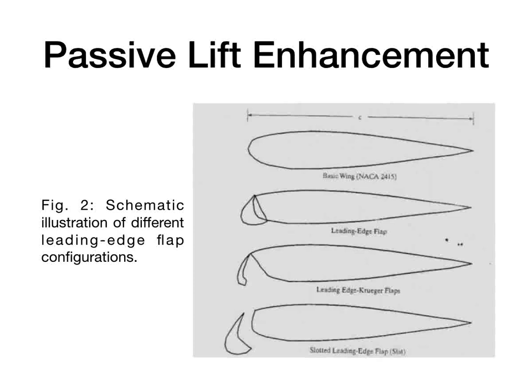A leading edge slot works the same way as a slotted flap, but allowing air from the high pressure lower surface to flow to the upper surface to add momentum to the boundary layer and prevent flow separation. Of these devices, leading edge flaps are more effective than slotted flaps on highly swept wings.